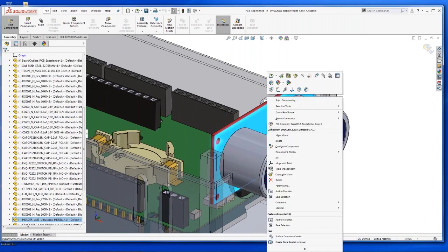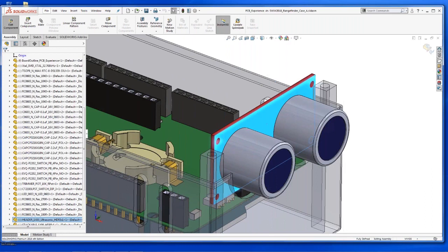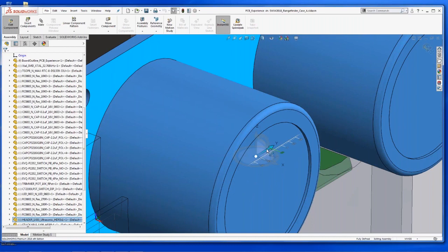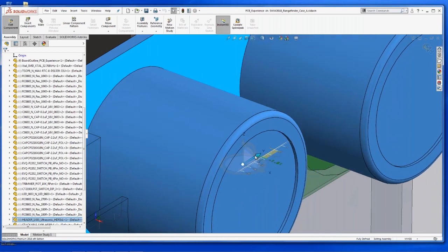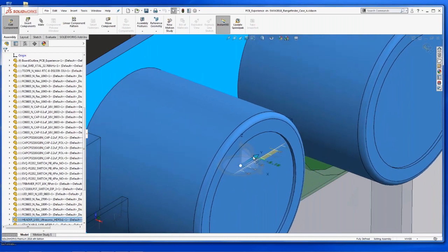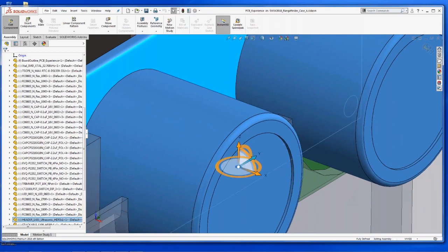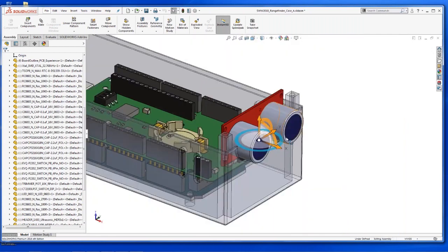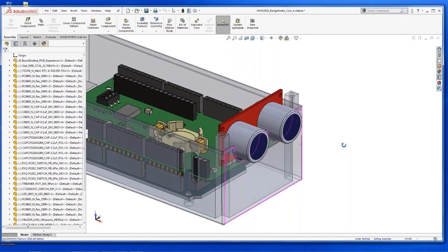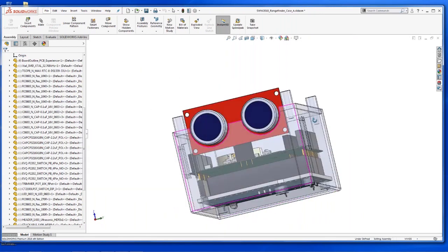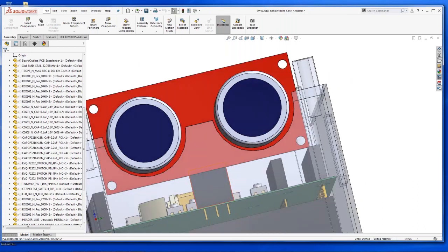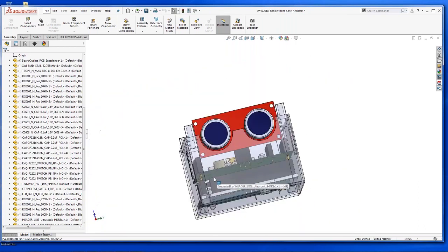I highlight the component and I tell it that we need to move it with the triad, right? Because we just need to move it in the Y dimension about, let's go 2.4 roughly. All right, that's close enough. So again, we could use SolidWorks tools to dimension it, center it, however we like. But for ease of quickness, we just visually centered it. Now our rangefinder connector is perfectly positioned.